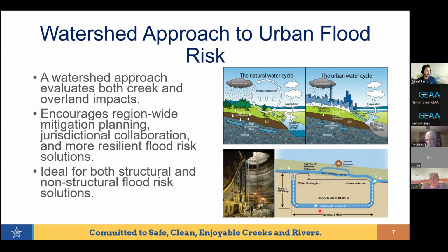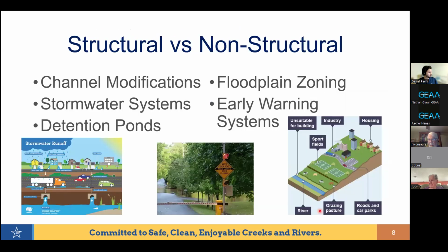So we're trying to identify a holistic approach. When we just have these 1D floodplains, we don't really identify where the flooding may be coming from. And so if you have these 2D floodplains, you can have a better idea of the whole watershed and identify where the flooding may come from, and try to have this multi-tiered approach of flood resilience.